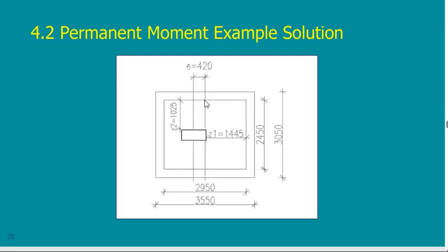This is the center line of the original footing, and this is the center line of the column, and this is the eccentricity. Based on having a moment in this direction, I just shifted the column in the other direction, so I canceled the moment. That's all.